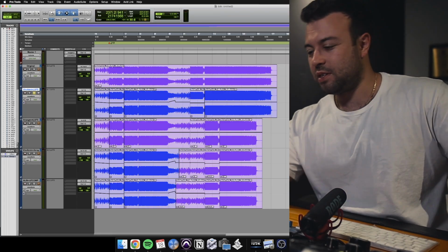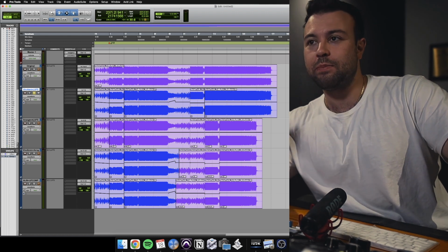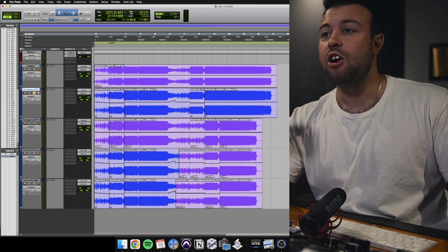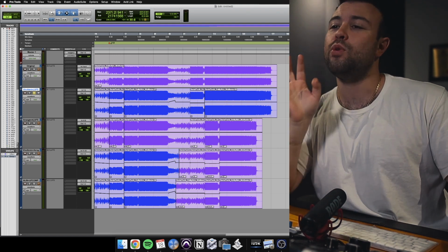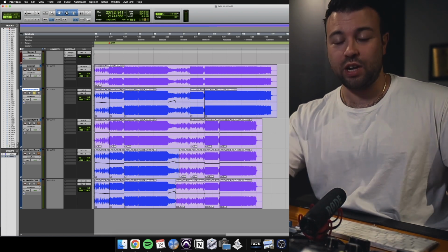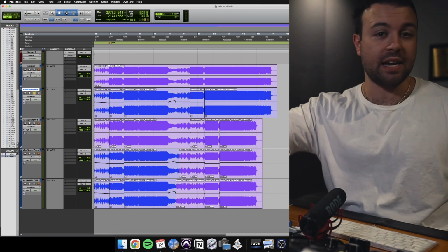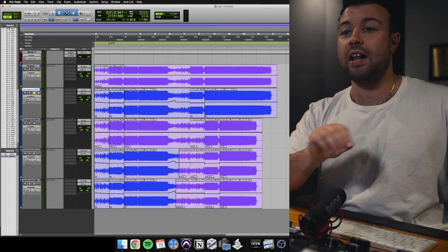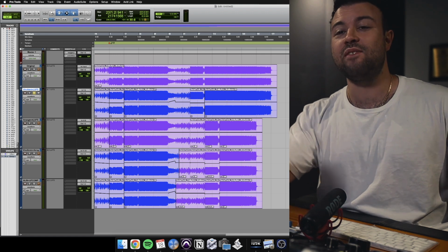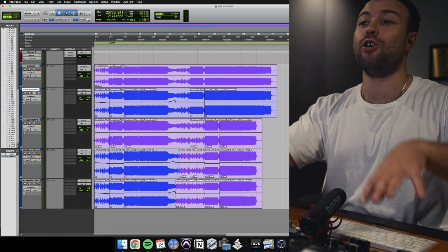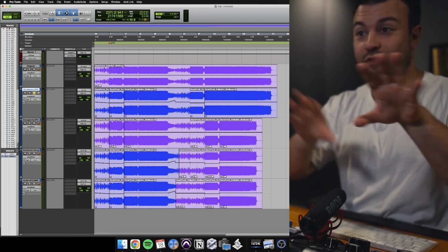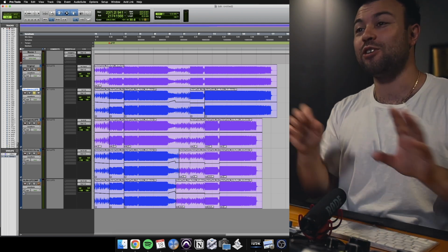We know a couple of things about loudness. So integrated loudness is calculated throughout the duration of the track. It is a sum of the averages of 400 millisecond chunks with every 100 milliseconds overlapping. Now, any of those values that are below -70 LUFS, as we've said, get gated out. They're not included. But also, given that we're using the ITU standard, which is what Spotify uses, any values -10 loudness units below the average are also just not calculated in the equation. So I did a few things to manipulate how we can change those LUFS readouts.